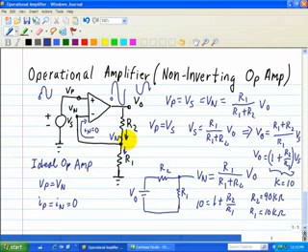The upper bound of 1 mega ohm comes about because surface leakage makes it difficult to maintain the tolerance in a high value resistance. Also, high value resistors are noisy, which leads to problems when they are connected in the feedback path. Hence, the 1 kilo ohm to 1 mega ohm range should be used as a guideline and not a strict design rule. Actual design choices are influenced by system-specific factors and changes in technology.